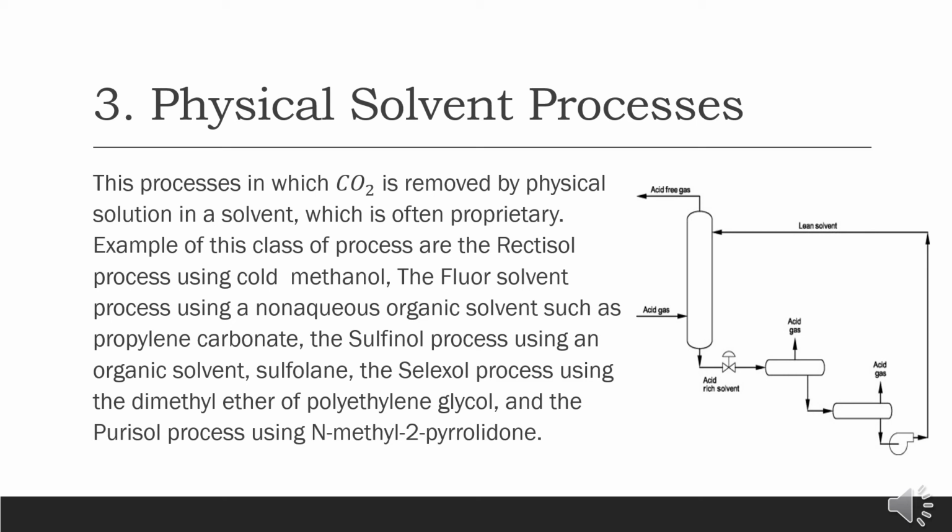Aqueous ammonia solutions have been used for removal of CO2 and H2S, particularly in the ammonia synthesis plant where ammonia is available. Water has also been used, but CO2 solubility is poor, requiring high pressure operation, and hydrogen losses because of the solubility are high.